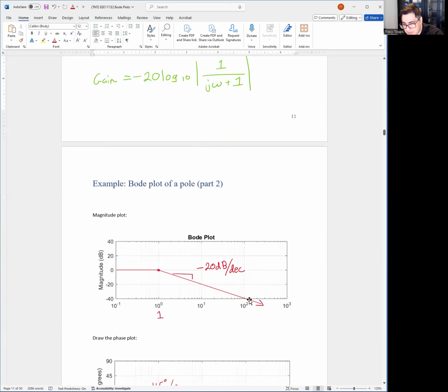Okay. That's why you see the gain go to -40. What's the gain of -40? -40 dB gain is 0.01. 99% of the signal just went poof. You killed it. Okay. So that's how the circuit ties into the Bode plot. It's just looking at the gain of the circuit based on how inductors and capacitors do their voltage division in our case. Okay.